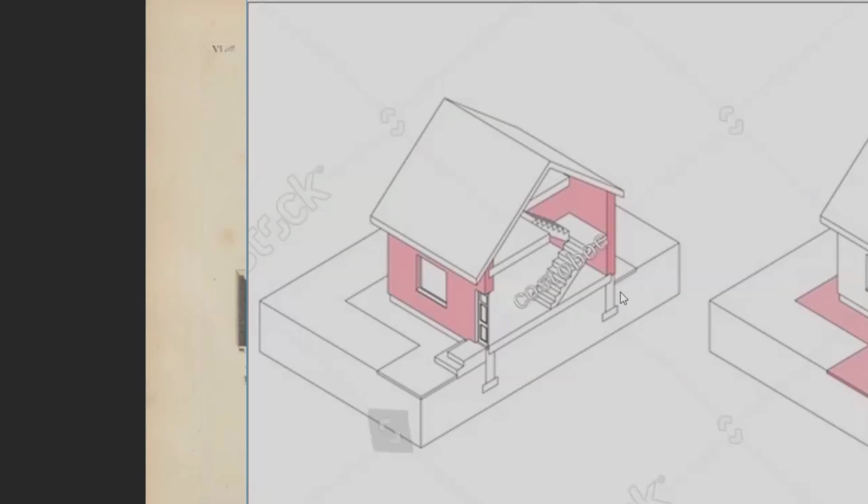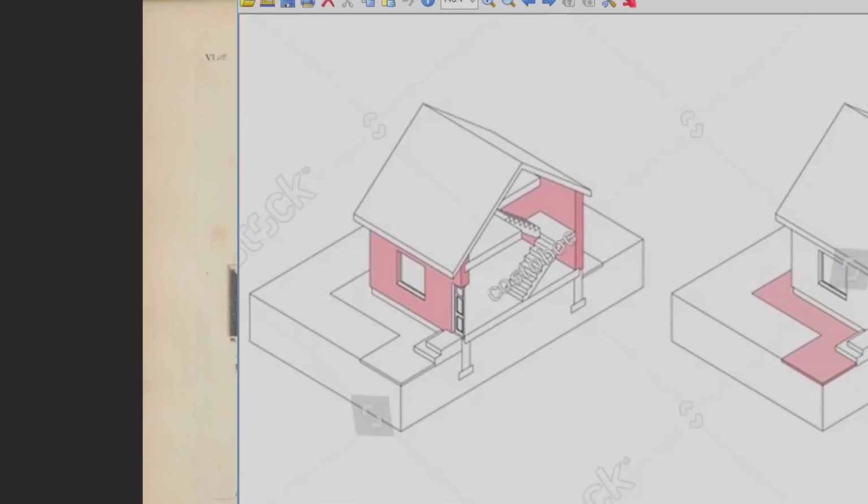If you go down to Florida and you're designing a building there, your foundations are a lot shallower because the frost line doesn't go as deep as it does here in Chicago. And if you're farther north, probably in northern Canada, the frost line goes much deeper than that. So that's just a quick little outline of a building section.